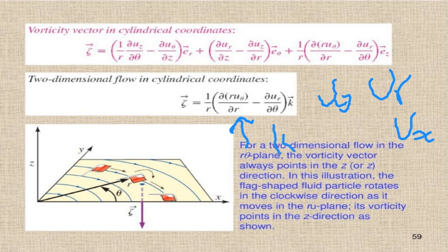Here also you can see that the fluid particles are rotating as they move along the path. And what is the rotation sign? What can you say about the vorticity? They are rotating clockwise, so it means that my thumb is showing minus k, so clockwise is always minus.